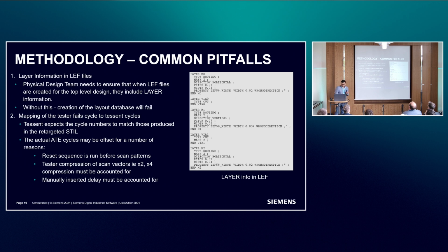Okay, common pitfalls. These are important ones, very, very specific to Intel. Some of them are common as well. When you request LEF files from the structural design or physical design team, ensure that you have layer information covered as part of your LEF files. Without that, your layer verification is going to fail, and we had a few iterations because of that. The other thing would be if you have a hierarchical core where you want to perform hierarchical diagnosis, ensure to write out your DEF files with component information. Without component information, you cannot do the layout aware diagnosis at the core level.